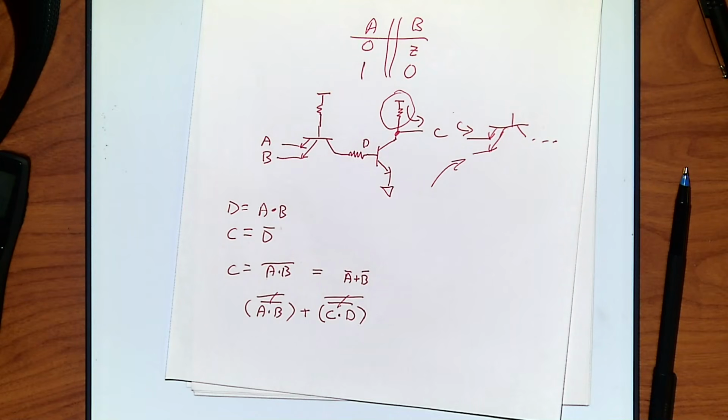They just supply zeros, and if all of them supply a Z, you will get a high output with whatever you supply your power to. You cannot possibly generate a problem with it because none of them supply power, so there's no way to short circuit if one's on and one's off. That does mean externally you have to supply power, for instance, a pull-up resistor.